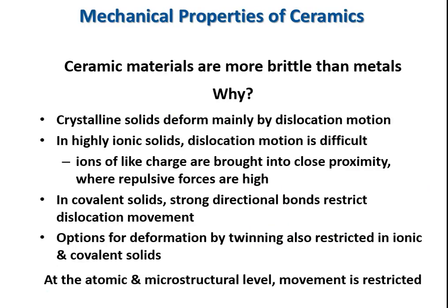Which brings us to ceramics. Why is it that ceramic materials are so much more brittle? From the first day of this class, you probably heard myself or another instructor talk about the dangers of designing with large, thick, monolithic ceramics and how they shouldn't be put in tension or in fracture critical applications. The reason that they don't have fracture toughness and why they can't deform plastically is dislocation movement is so very, very difficult.